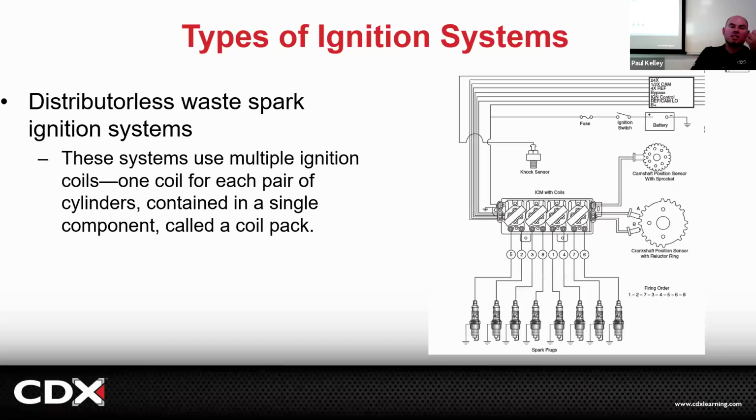So this is a little early still, but the ignition control module is going to be like, all right, cylinder number 5 is at 10 degrees before top dead center. What should we do? Oh, I know. Turn off the ground to the primary coil, which will induce the voltage into the secondary coil, which will do what to spark plug number 5 and 2?